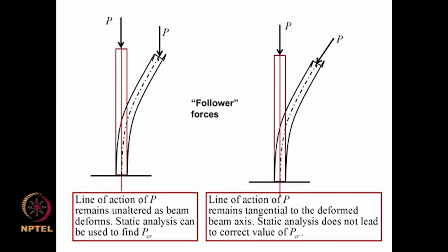We also considered another class of problems wherein the loads were not time dependent, but the direction of the load was. For example, if the load P does not change its direction during the process of deformation, a static analysis would tell us how this structure behaves. But if the load remains tangential to the deformed axis, a static analysis reveals that this structure is always stable, but a dynamic analysis shows that there is a finite value for P beyond which the structure becomes unstable, which is consistent with what we anticipate.